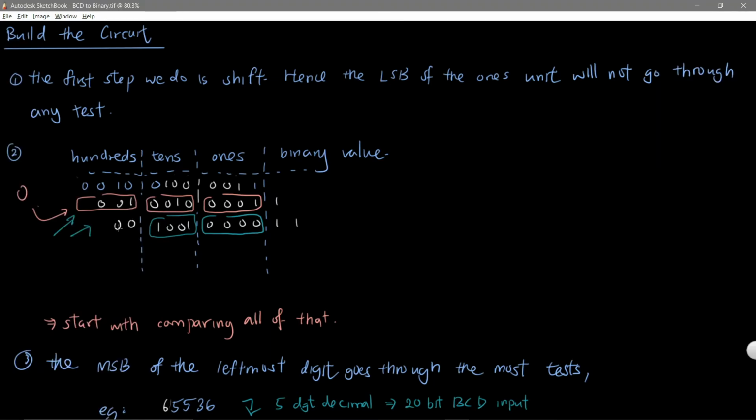So if these are zeros, you can actually just cut them off. So in the process of building the circuit, you have to be aware of little details like this. Converting case-specific values is going to have specific circuits, but if you are generally converting 8-bit or 16-bit or 32-bit, you want to expect the maximum value possible, so you want to cover all the values. So if you are building it for a general purpose, then you need this case here as well as here, because who knows, the values will be 1111 here, right? Alright, so move on.